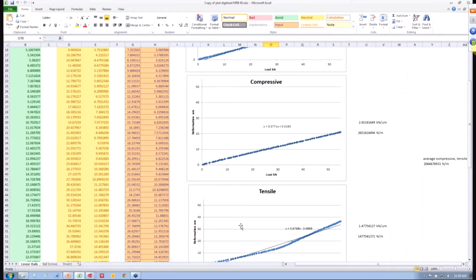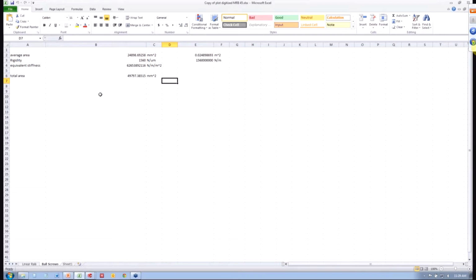For the ball screws, again, we were given just a single rigidity value. And in SOLIDWORKS, we have to convert that rigidity value due to the inputs that I'll show in the setup. We had to make that per unit area, and what SOLIDWORKS Simulation uses is the average area between the faces that you select to define the spring connector.